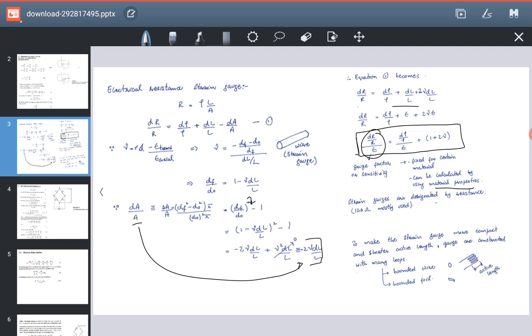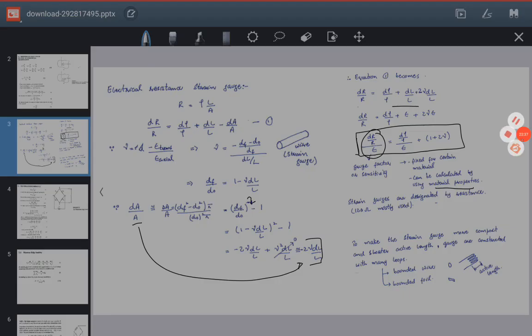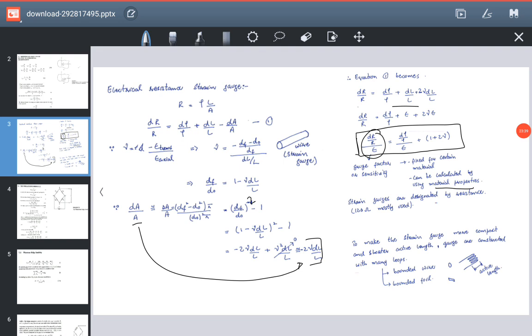Normally the strain gauge that is currently being produced is made up of, wait a second, let me check. The most precise gauge which we are able to form, and which is being commercially produced, is the electrical resistance type, and it is made up of ultra thin foil which is photo attached. It has the length of 0.008 inches. So yes, the material matters a lot when it comes to measuring gauges.